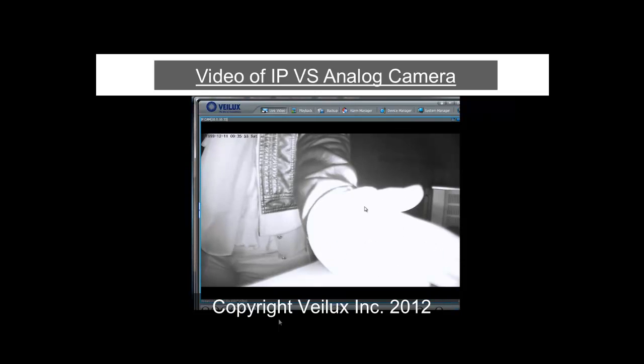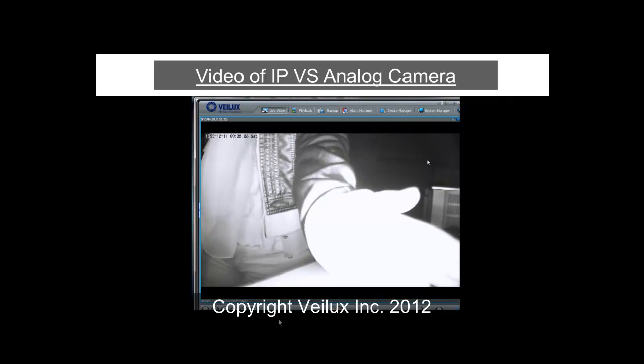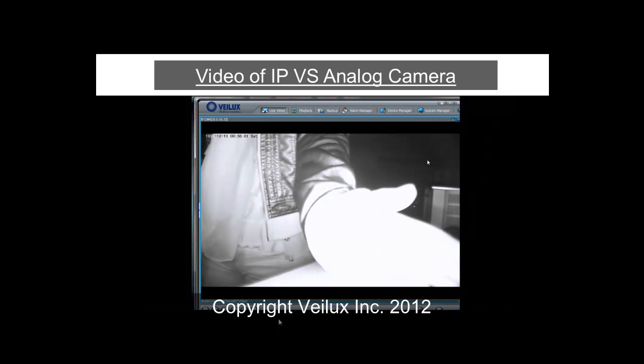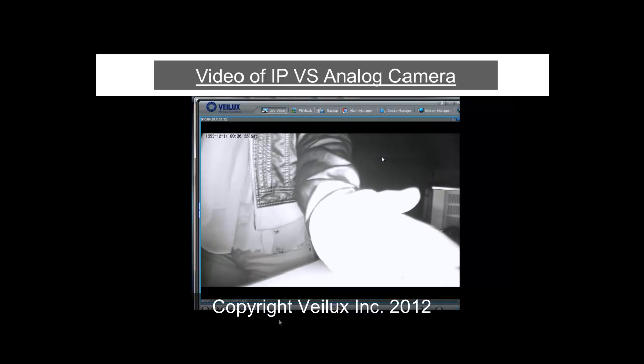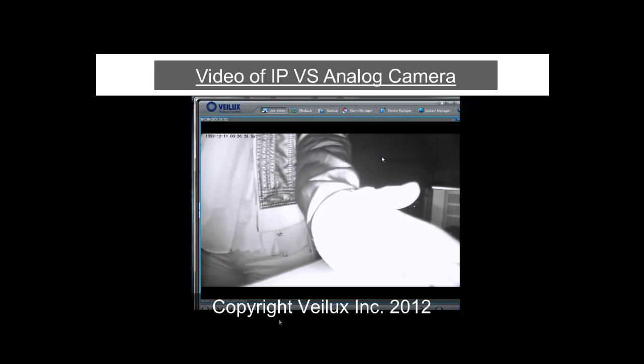Once she got up close to the camera with her hand and everything, you noticed the background turned almost completely dark. This is called smart IR. What happens is smart IR recognizes motion when something is close to the camera. Therefore the IR automatically adjusts to focus on the item up front, and not always everything full bright and washed out. So it's got more focus here, less focus on the back, so everything's not brightened and washed out. This is a function called smart IR.